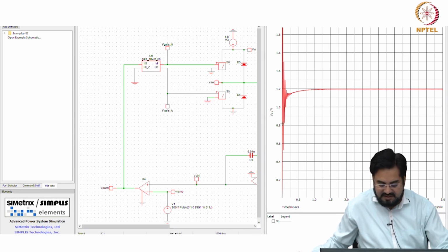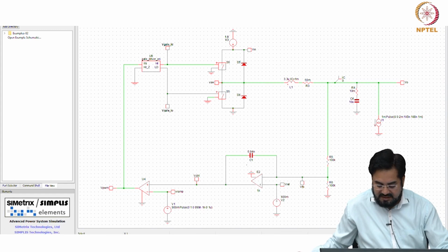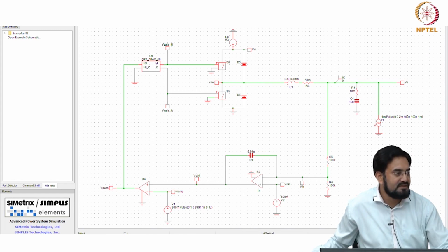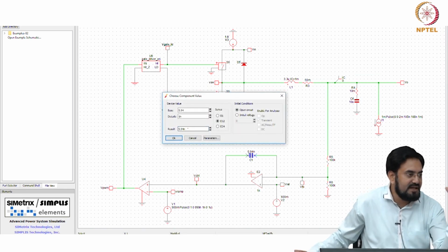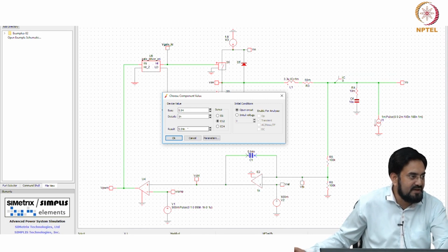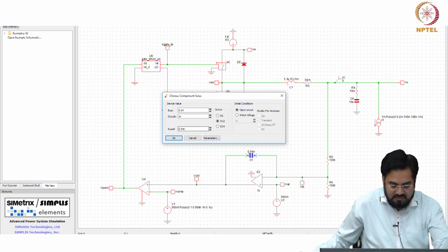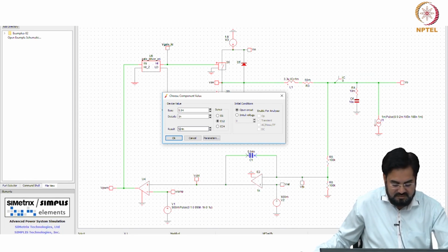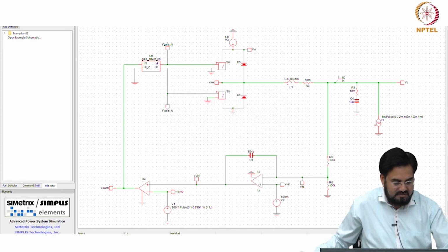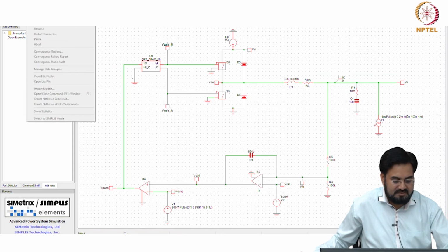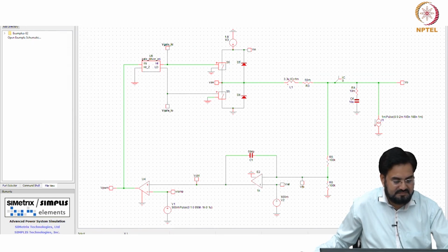It goes away. If I keep reducing the gain or increasing the value of this capacitor, then that ringing should reduce. Now let us say I do not include that 10 factor, meaning 0 dB gain margin, then what should be the value of this? One over 10 times, correct? So it should be unstable with this, so we can check.